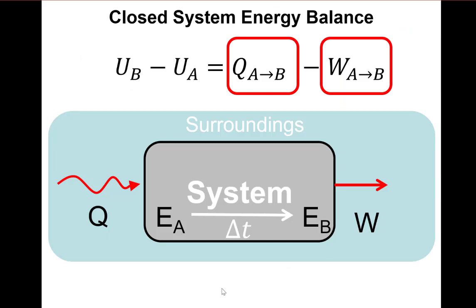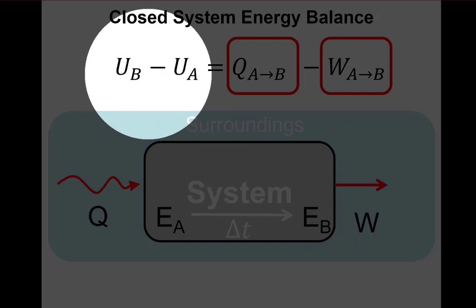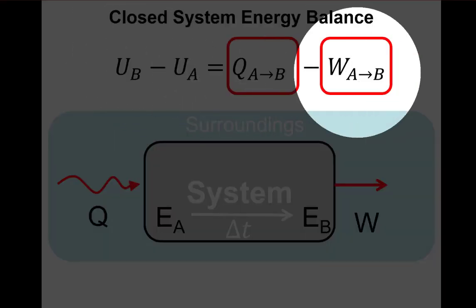So when we talk about the first law, at least after we make some assumptions about kinetic and potential energy here, we're going to get that delta U is equal to Q minus W. Now, the good thing is, at least for the Otto cycle we'll talk about today, we don't have to find Q and W the way we did before.